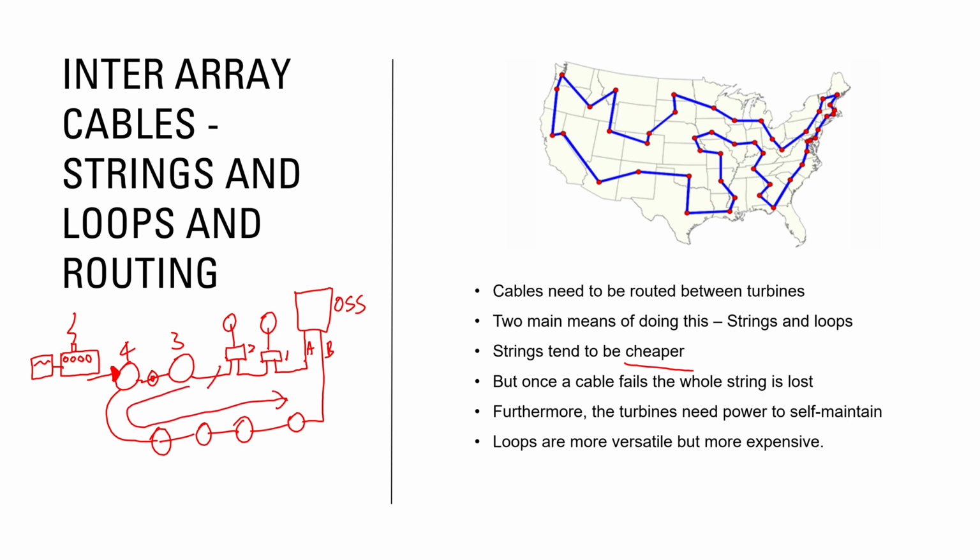For example, if we have a failure here, now the actual degree to which you can export power the wrong way down a string is dependent on how the cross-sectional area of the string works out, because of course you still want to save as much money as possible, and you still do not want to use larger cross-sectional areas than needed.